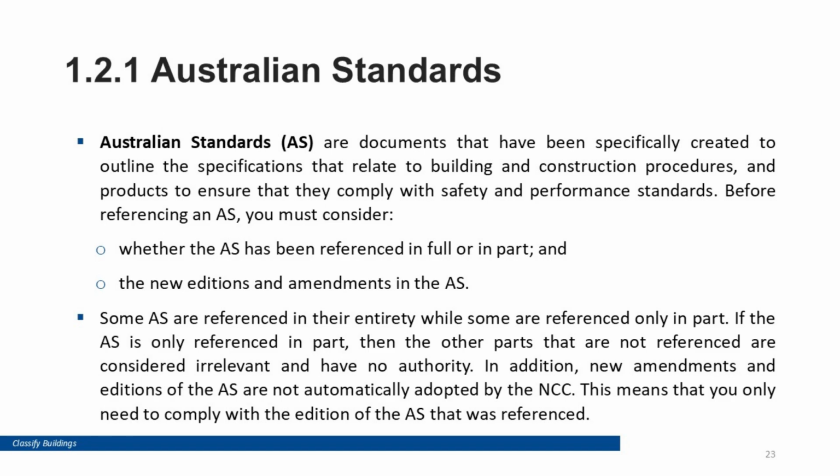Australian standards. Australian standards support construction quality and compliance. When using a standard, always confirm whether the standard is referenced in full or in part. Which edition, amendment, is the one adopted for the project? This matters because not every update is automatically adopted into the NCC.